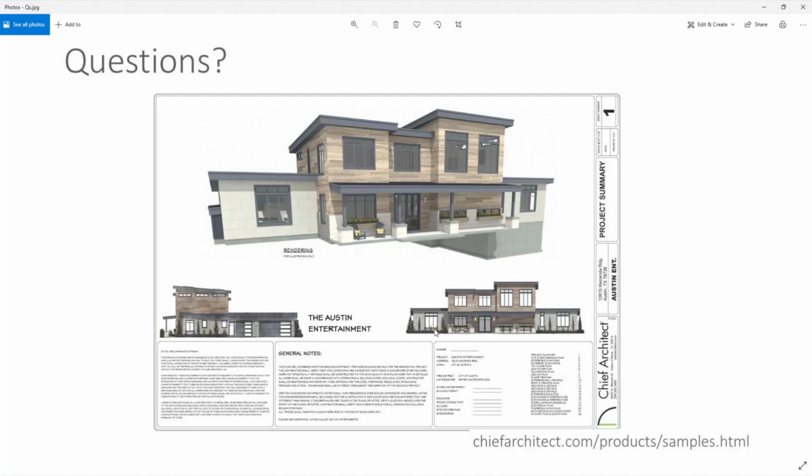Roger from Southwest Colorado. A couple of questions, and one will relate back to the automatic roof joining. First off, is there a particular parameter that I need to set so that when I'm joining a roof against an exterior wall, the contact point is at sheathing as opposed to cladding?